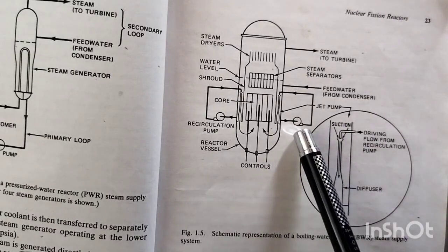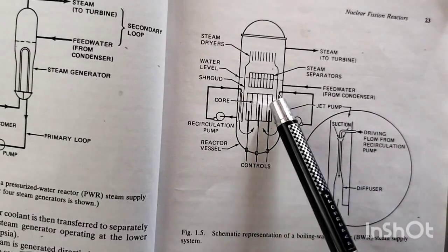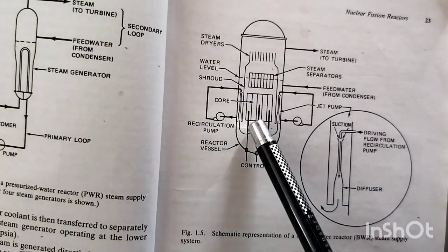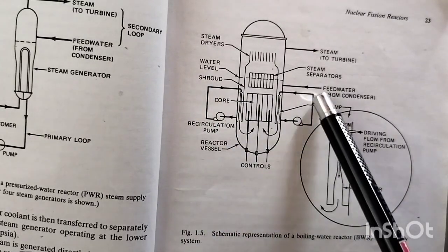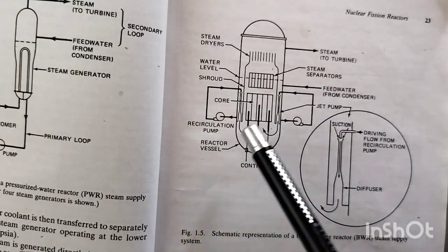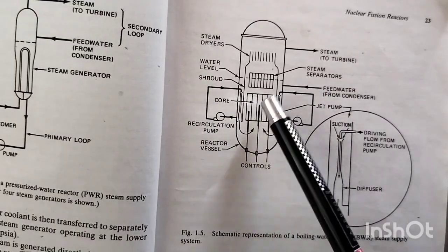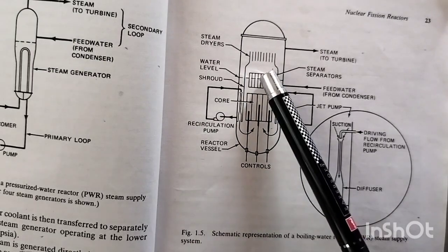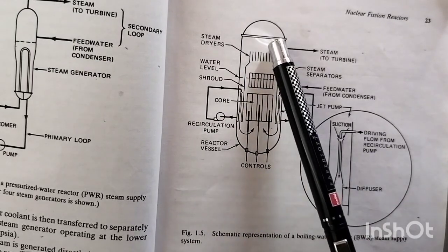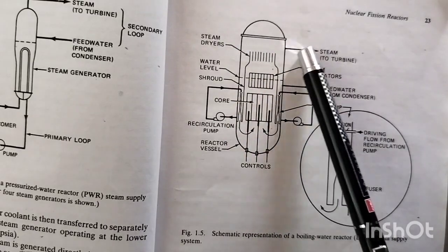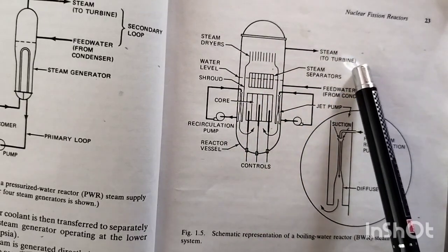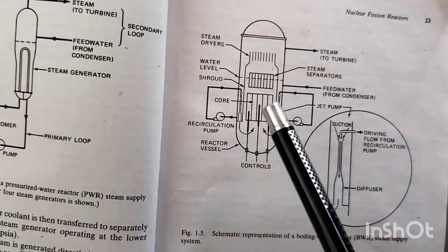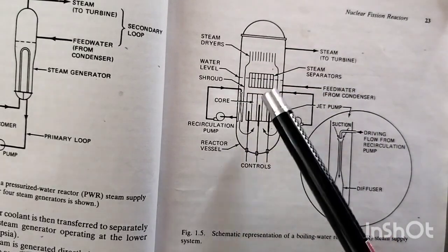So here we have a pump, it is recirculating the existing water. Okay, this is also another pump, recirculating. It is like this, both the sides, these are recirculating pumps, because we have to maintain always the reactor core inside the water. Above the reactor core only the water will be boiled. So this boiled water, that is nothing but steam, goes to the turbine, rotates the turbine, condenses and comes back here. So it will maintain the water level always above the reactor core.